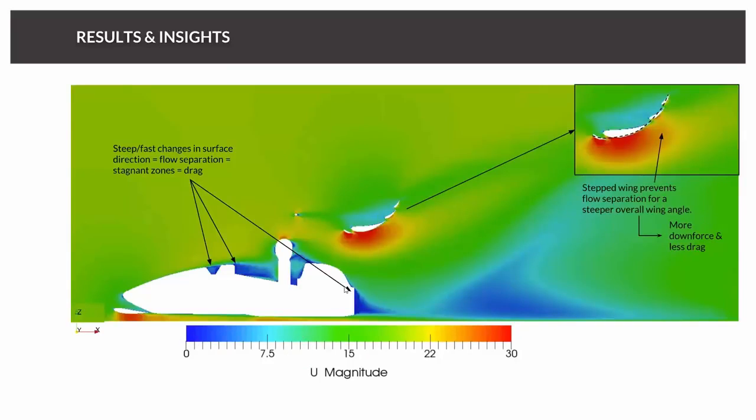If you now try to understand what we could improve at the car, first of all, we see that we have some flow separations. Here, here, and here. And they are absolutely unnecessary because there is no need to have a flow separation here at the car. And this is the car of a team from 2015 or 16, which was sponsored by SimScale. And actually, a lot of things came out, which were very easy to optimize, but nobody saw them before because there was no simulation available.